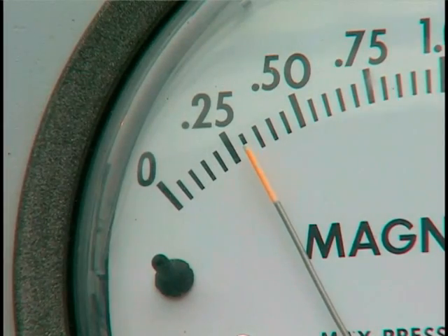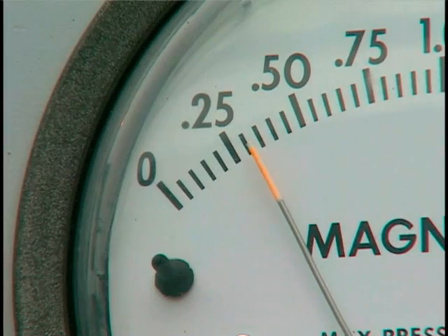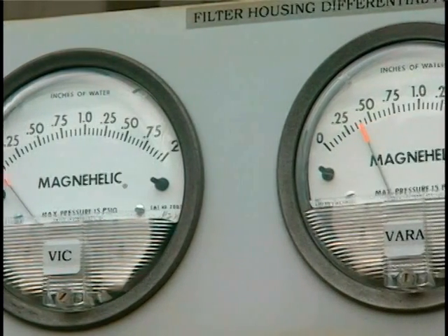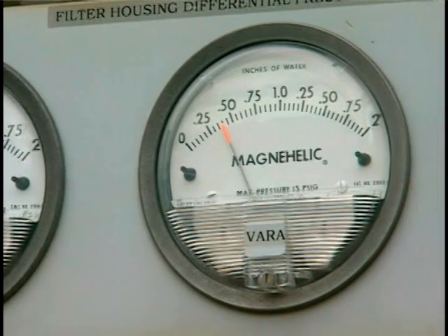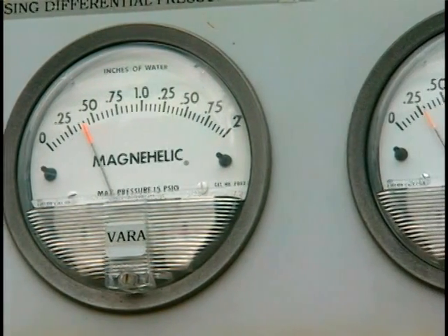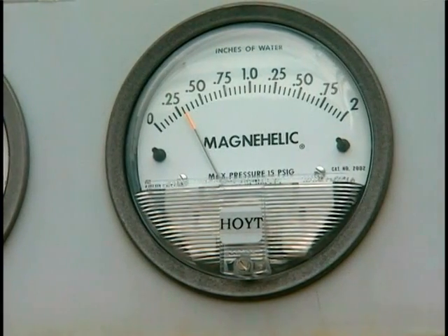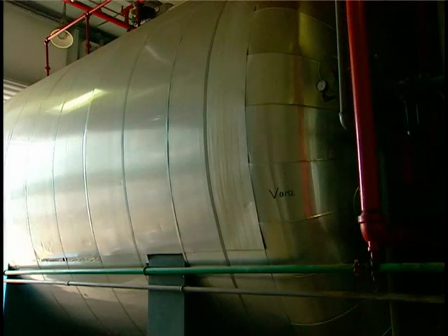The pressure drop across the carbon bed should be evaluated. As the carbon bed ages, it settles and compacts, causing the pressure drop to increase from baseline values. Since old carbon may have less capacity than new carbon, an increase in static pressure drop may indicate reduced performance.